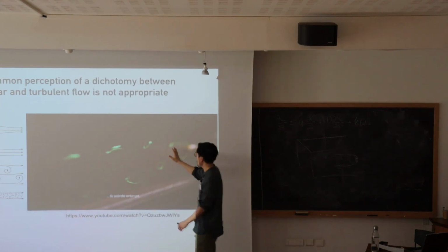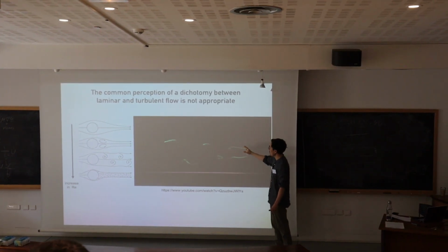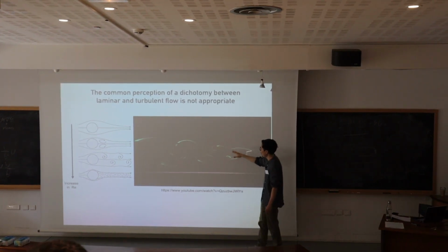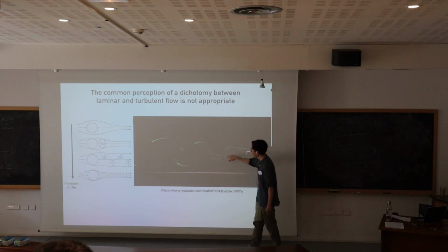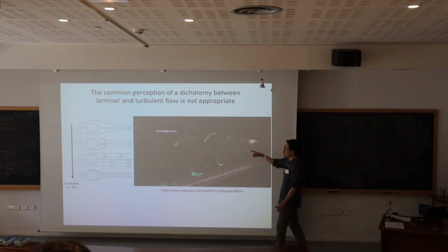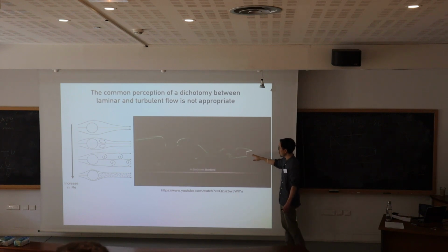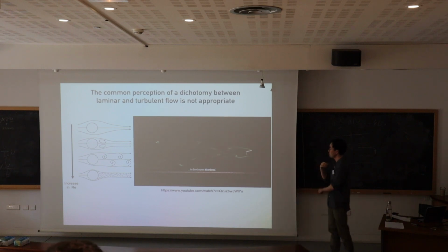So this is now, you see the change in pattern, right? And this is unsteady laminar flow, but still predictable, right? It became a little more dynamic, but still the pattern repeats, and nothing is chaotic. It's only when you increase Reynolds number up to 10 to the 5 that you start to see chaotic motion, which will soon appear.